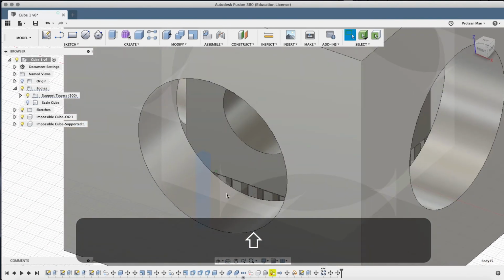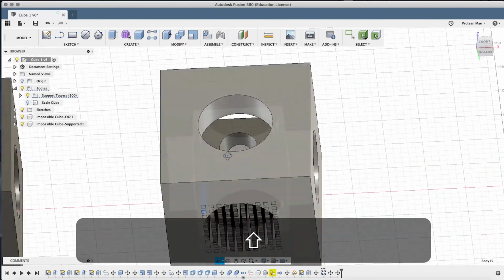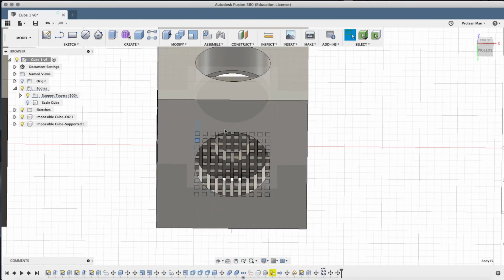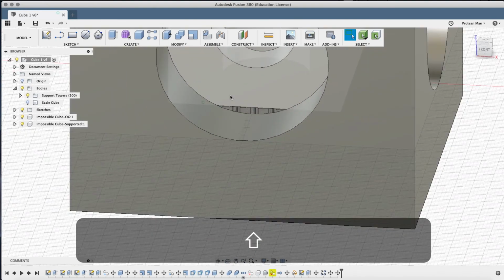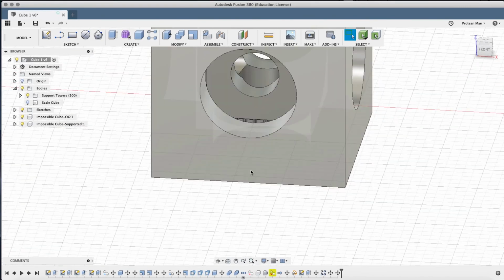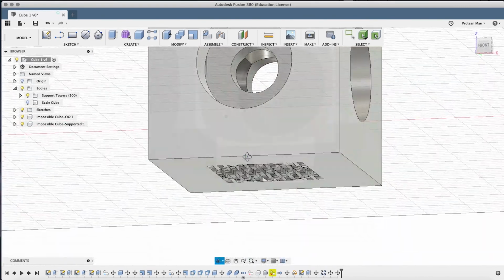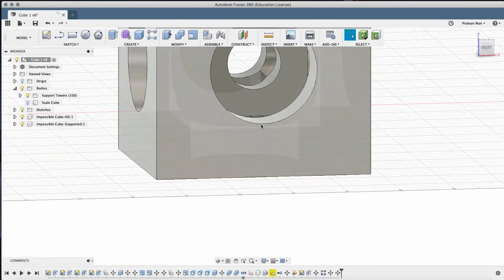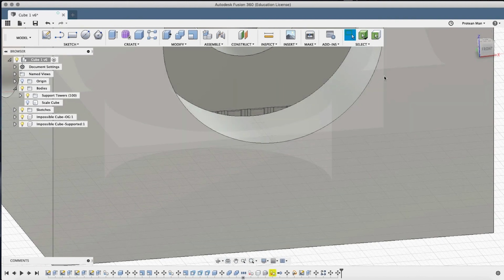So what we're going to do is do a few different things. And this is sort of a removal process to make the perfect distance. So remember that we had the 0.2 distance here. And again, if you're thinking, why are we doing this if the slicer does this automatically by itself? Well, it's nice to know, one, how 3D printing works, because a lot of people that use Fusion will be using 3D printing. It's also nice to know how to do these different processes in Fusion. This is a good way to practice it.